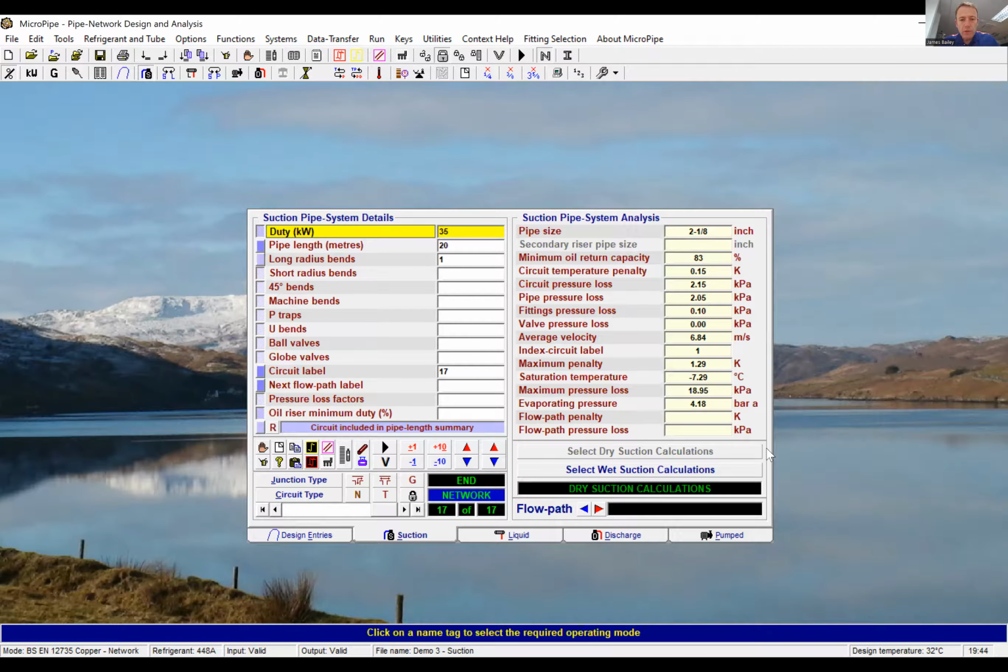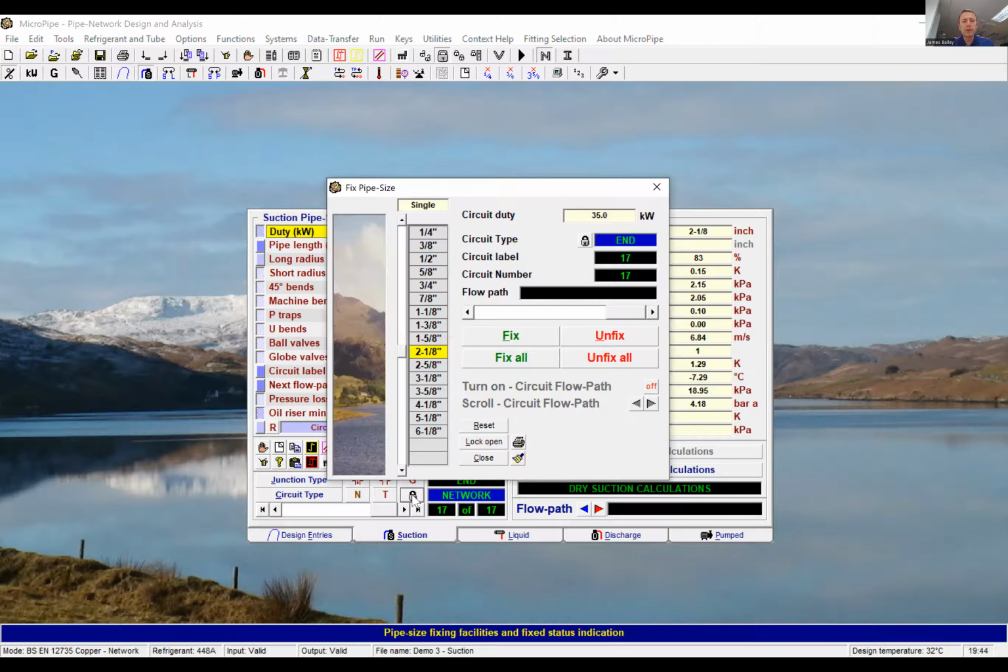What I'd just like to concentrate on now is to come down and show you some of the riser sizes. On 1 inch, we've got 11.3 meters per second, so we're well within the tolerance band that I look for as a designer. Again, 15 meters per second. And I think we've got one. Nope, they're the risers. I fixed all this pipework. Now I'm going to unfix everything.